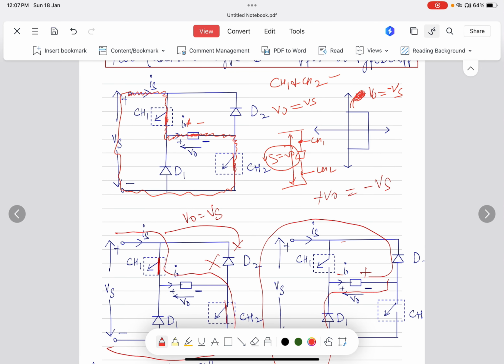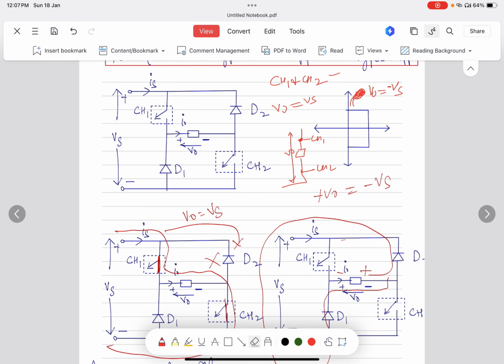Now when both choppers are off, the inductor, which was already charged, changes polarity, because an inductor does not allow a sudden change of current. So it changes polarity and the current starts flowing through the diode D2, then through the back path to the supply and D1. So that means the diodes D2 and D1 are conducting.